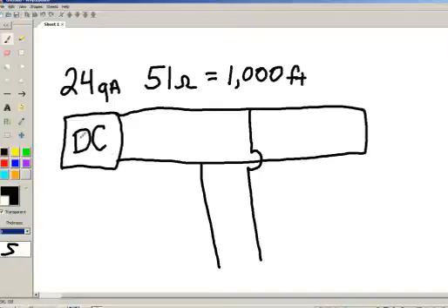Well, here's part number 2. Instead of a short, we have an open. And between us and the open is that same unfaulted bridge tap. Okay? Well, if it's an open, we don't care about gauge and ohm values anymore. All right. So here's my open. Between me and my open, I've got that same bridge tap.